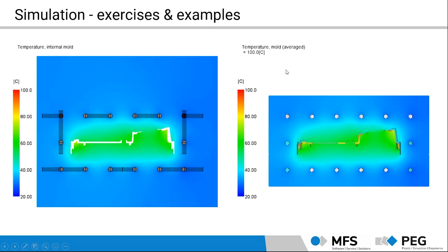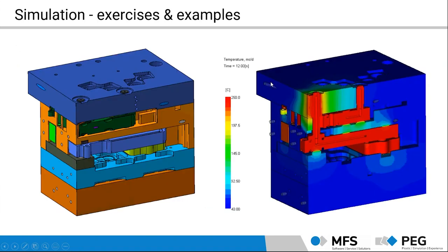And during this training, we will of course have more complex things to discuss, and that is what I just want to show you with the last picture here. A fully 3D meshed mold with all components like the hot runners, the different mold plates, mold inserts, and also the elements to keep the hot runner away from the mold itself.